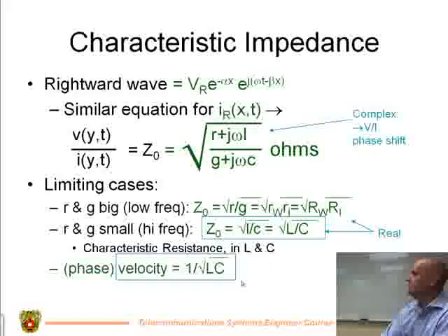In general, we're concerned with mostly high frequencies. So our phase velocity is 1 over the square root of LC, which you've seen before, right? What was 1 over the square root of LC? It was omega naught, which is the resonant angular frequency. Yep, exactly. Wait, no, yeah, you're right. Omega naught was 1 over the square root of LC.